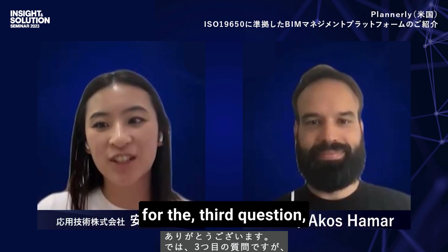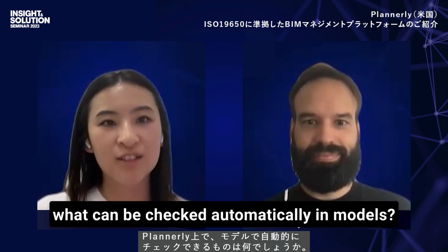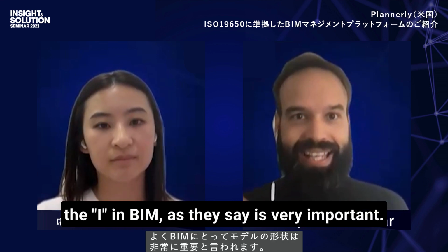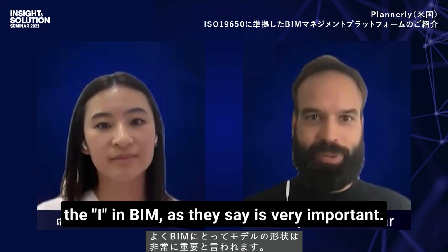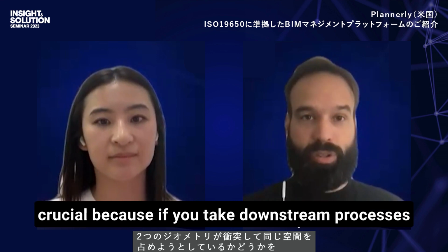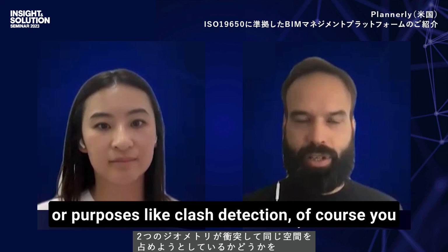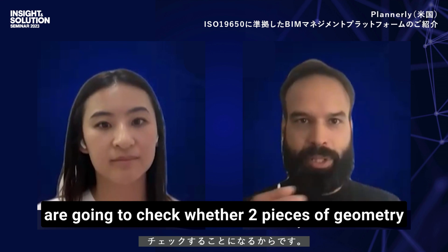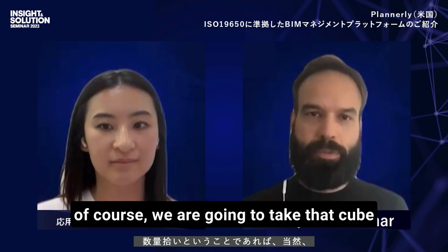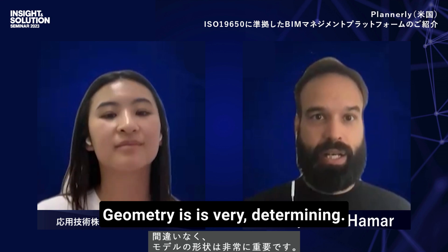Thank you very much. For the third question, what can be checked automatically in models? So you were talking about verify functions, right? The I in BIM, as they say, is very important. So we can talk about geometry. And of course, geometry is really also crucial, because if you take downstream processes or purposes like clash detection, of course, you are going to check whether two pieces of geometry are colliding and trying to occupy the same space. If we are talking about quantification, of course, we are going to take that cube and calculate the quantity of those. So geometry is very determining.